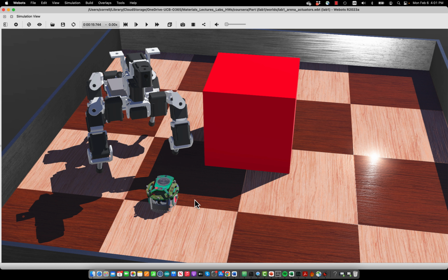In Webots, motors are abstracted by a device which can be operated either in position control, that is, you set a certain position that you want the robot motor to turn to, or velocity, which is given in radians per second. We can best explore this by actually playing with the robot controller, which we will introduce now.